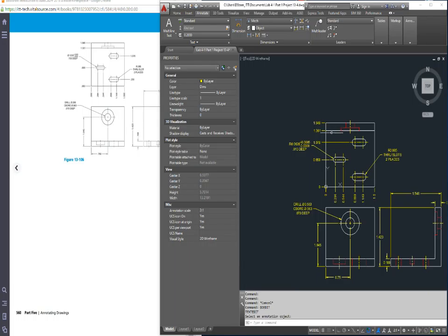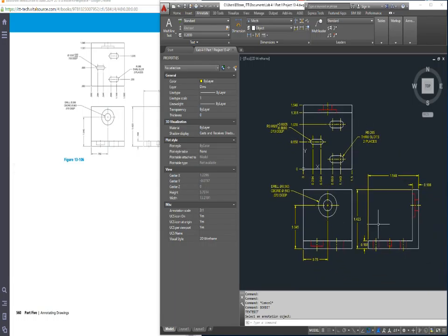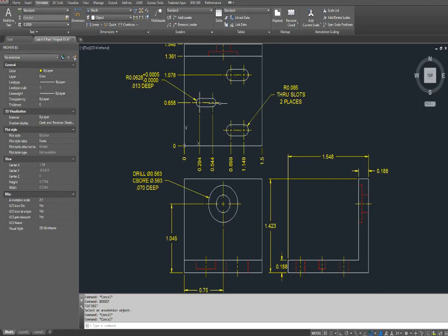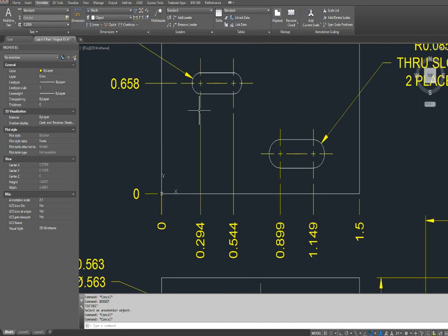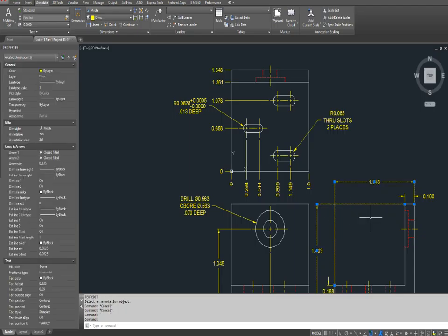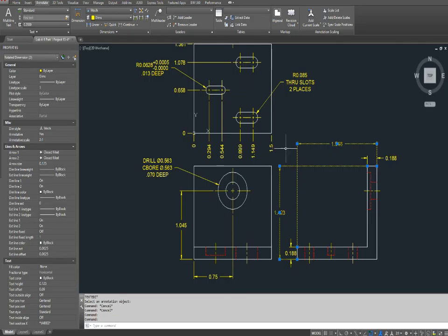So there's your ordinates. Now you've fixed your LT scale. Your drawing should look exactly like this. Exactly like this. Make sure that your center lines are correct, that there's a gap between your dimension and the object you're dimensioning to. So like here, I can cross these dimension lines because I'm crossing dimension lines, but I want to try not to cross my radiuses through any other ordinate dimension or through any other dimension. This is a typical area where a dimension may cross, but it doesn't happen in a lot of places.